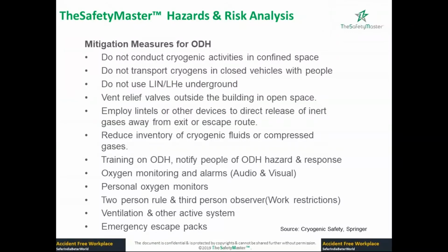Do not transfer cryogen in a closed vehicle with people. If you're carrying a liquid nitrogen tanker or cylinder inside a closed vehicle and there are people inside, then no. You also can't use liquid nitrogen or liquid helium underground. For example, in Europe, if you want to transport a liquid nitrogen tanker through a tunnel, it's not allowed. You understand? He has to take a different route.